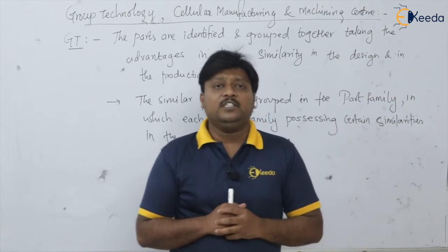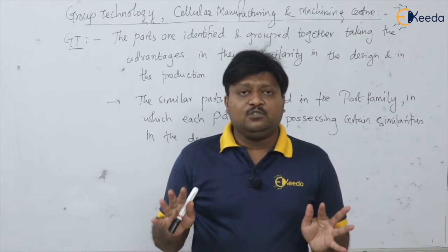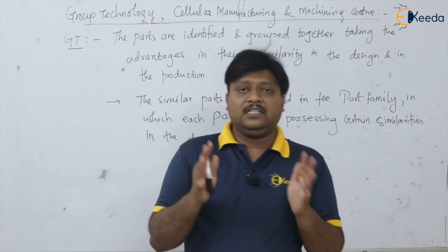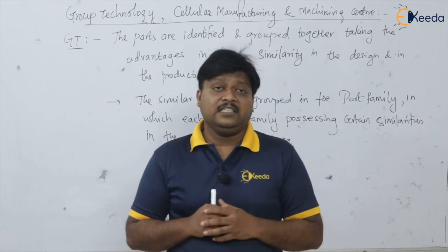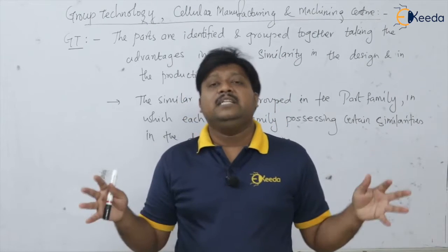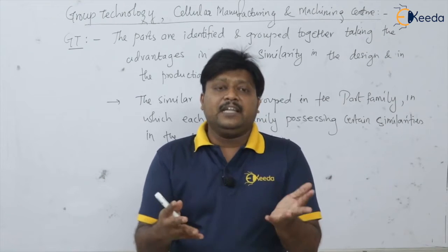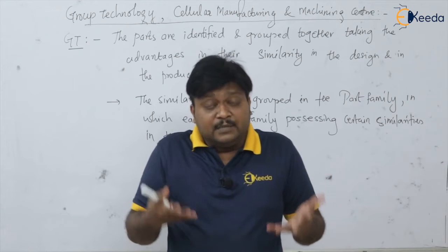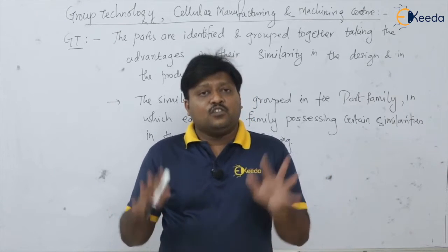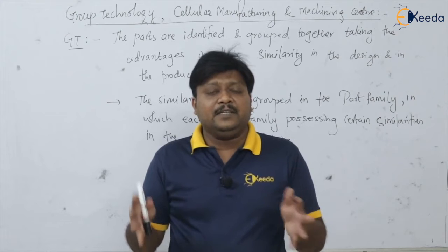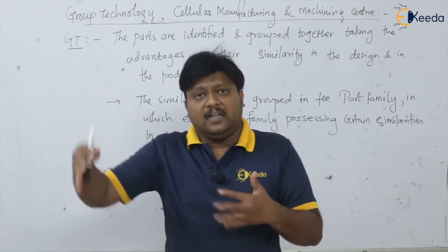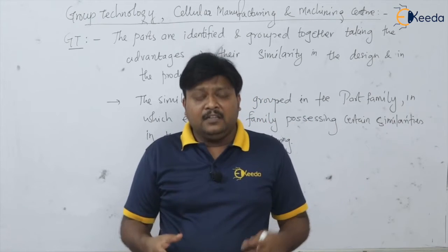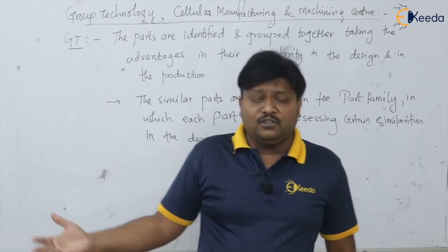So this is about group technology. So dear student, what is group technology? When the word group technology comes, the word part families should come along with it, based on certain similarities. Where should the similarity be? Either in shape, geometric shape, size, manufacturing process, designing process. So parts that have similarity in certain criteria, what do we do with them? Sit them together, keep them together. Even we can have different shop floors.